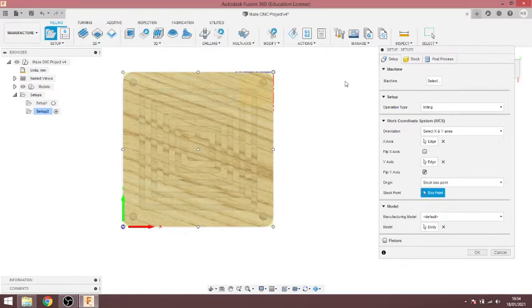So if you imagine the cursor is the cutting tool, you would then line that up. Good practice, line it up with the bottom left, because that's the easiest part to reach and measure and check you've got it in the right position. And from there you can then start your cutting operation, and when it finishes it will return to the home position.